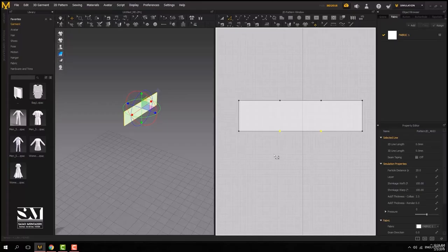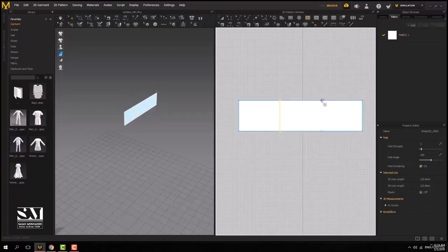Very good. Now I can connect these points using internal lines. Select the tool, click and double click, click and double click. But if you have too many points, it doesn't make sense to manually connect them one by one. So here, what should I do? I'll press Ctrl plus Z and again Ctrl plus Z to undo.